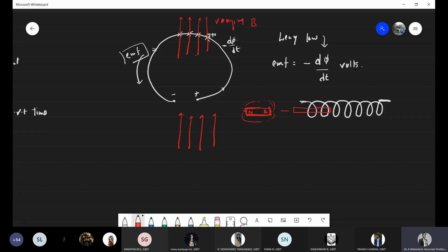So if I try to move this, these flux lines will disturb the charges or particles on the surface of this conductor, and there will be an induced EMF. There will be an induced EMF when you vary this magnetic field inside this coil, or this closed path. You're moving this magnetic field here. This kind of EMF is called transformer EMF, where B is varying. Is it okay?